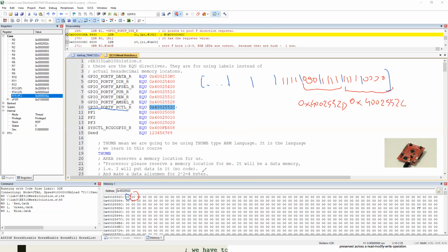So actually, when I say this 32-bit control register is mapped to this address, I mean it starts from this address. The first byte is this address. The second byte, the third and fourth nibbles, are the next address. The fifth and sixth nibbles are the next address.